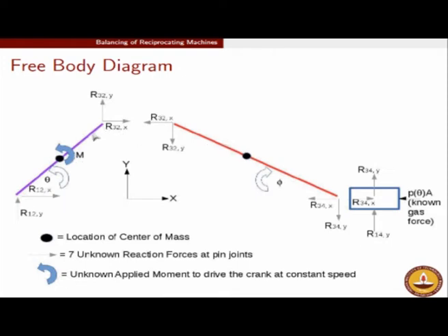The connection between the crank and the connecting rod is through a revolute pair. Through a revolute pair you can only transmit forces, you cannot transmit any torque. The other part which connects to the crank is the frame. So if this moment cannot come from the connecting rod, it comes from the frame. Therefore capital M is the moment applied to the crank.